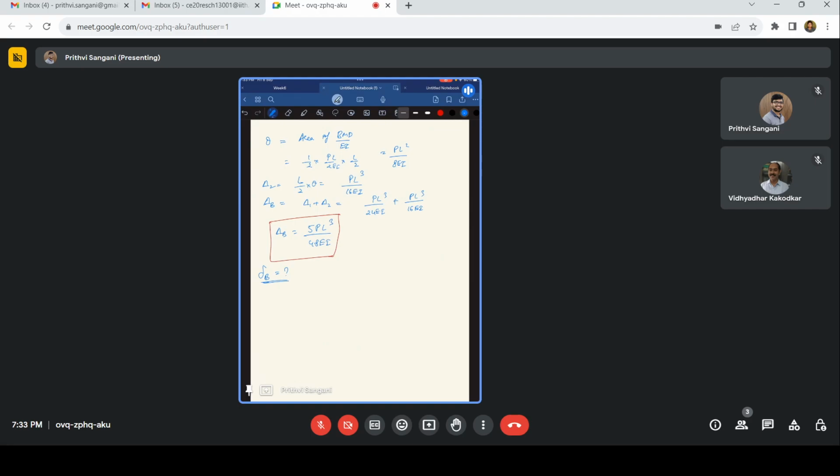In this I think we didn't solve. Let me solve it here. So we now have MB. There is no shear force. Again, this is frequently asked in most of the exams. They'll just ask, in a cantilever beam, if you apply a moment, what is the shear force? There will not be any shear force. There's only bending moment. So this is also a case of no shear force and only bending moment. What is it called? Pure bending, right?